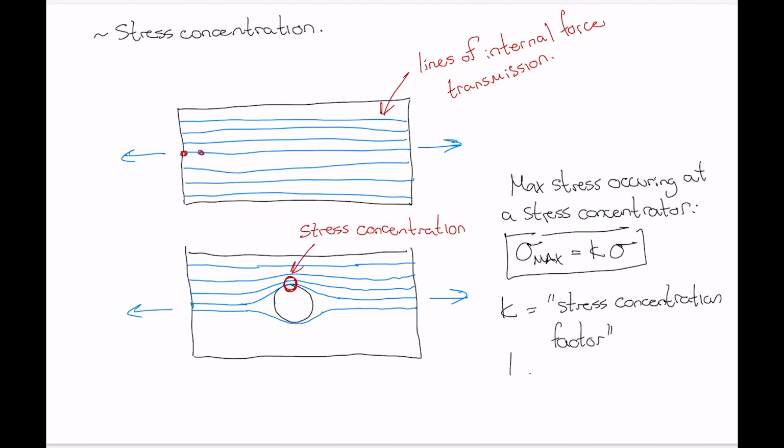And we get these from stress concentration tables. We get them from tables, right? The values of K don't have anything to do with the material that something's made out of. They just depend on the geometry of the stress concentration feature that you're dealing with.